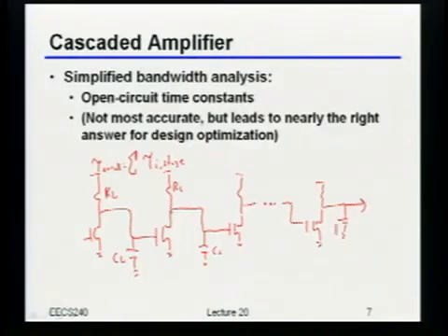So if my load capacitance and my input cap are basically the same as each other, then you can kind of think about it. There's no reason why any of these should be different, right? Because if you made any one of them, let's say, slightly lower bandwidth, it would limit the bandwidth of the whole network, right? If the load cap is a little bit bigger than the input cap, then you might actually start playing some games in terms of the sizes of these things.